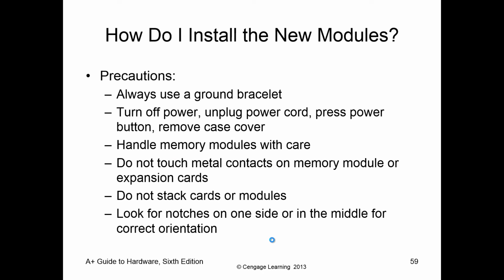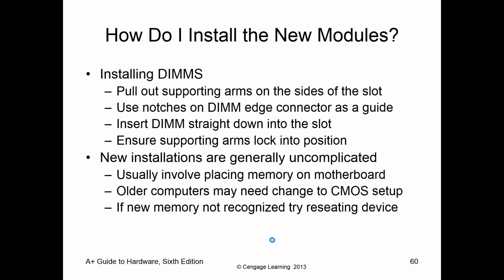So how do we actually install it? Use your grounding bracelet, take off your jewelry, turn off the power, handle the memory module with care, don't touch the metal contacts, don't stack the memory modules on cards or other modules. That's kind of subjective, but I mean, be careful with them. Line the notches up and install. You'd install DIMMs the same way.